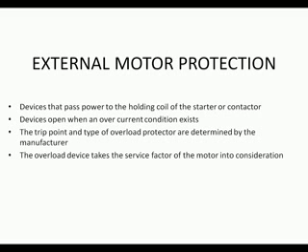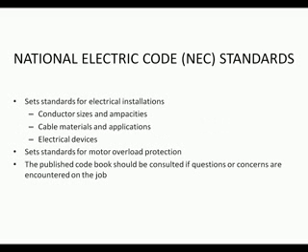Inherent motor protection are internal thermal overloads. They're usually embedded in the motor windings. They'll open on a rise in temperature. They can also be thermally actuated bimetal discs. They're positioned so the contact is made between the bimetal control and the motor. The snap action opens contacts if the motor temperature rises above a desired level. Either way, they shut off the motor.